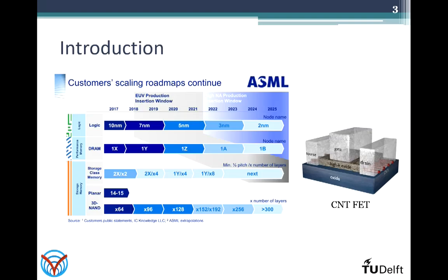But when the size of the devices approaches a few atomic layers and the conductive parasitics are reduced to the minimum, the impedance level exhibited by these devices is extreme. Because of this, it's not always possible to accurately measure these devices with a conventional setup that is usually based on a vector network analyzer.